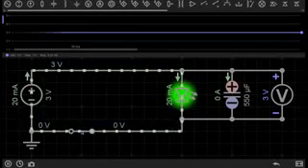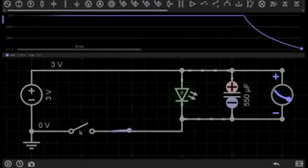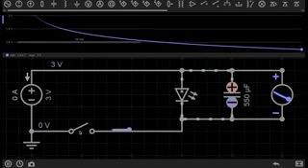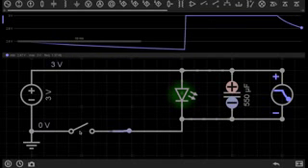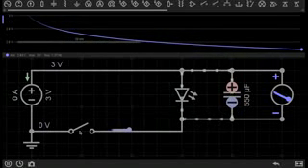to 3 volts. When I now flip this switch, what will happen is the capacitor will then start feeding this LED, as the capacitor is acting as a power supply for this LED until the voltage of the capacitor is too low to power the LED. So watch the voltage of the capacitor up here as I open the switch on this circuit. You can see as the LED fades out, the voltage of the capacitor is dropping. So the capacitor is charging up, and when I open the switch, it's discharging through the LED, which is why we see that fade as the voltage in the capacitor drops.